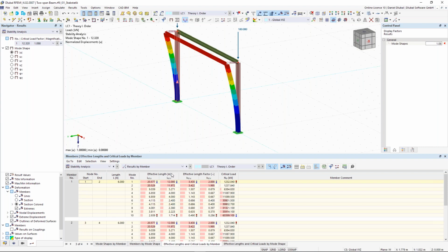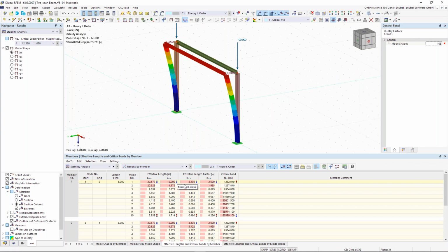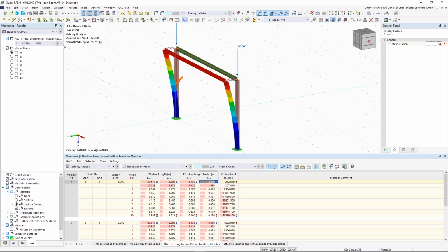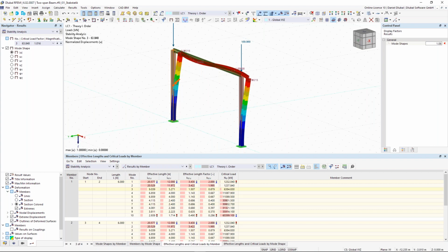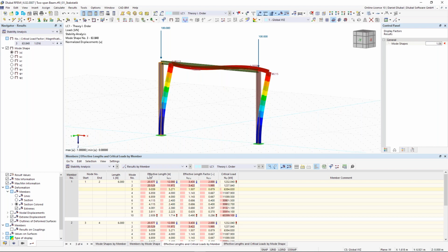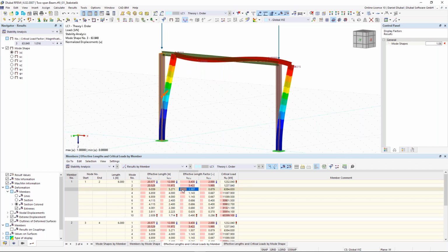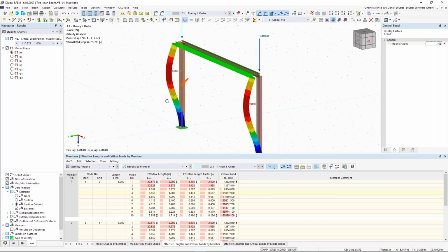effective lengths. When I would perform a stability design of steel members, I would take these effective lengths, and this is 2, because here we have our Euler case 1. The next one, for example, here we have buckling length mode 3 of 1.5 around the strong axis. So when I would do a stability analysis of this steel column, the equivalent length or effective length would be 9 meters. So maybe you can also take another look at that one.